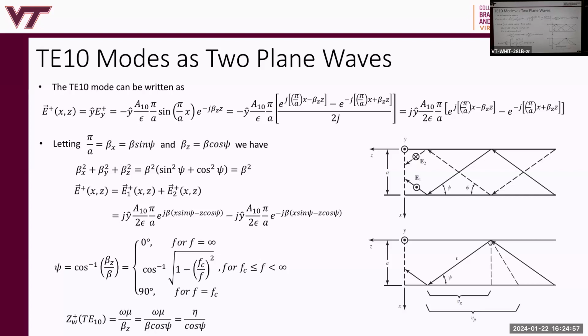So if I designed something like that in simulation and wanted to measure the reflection coefficient in an infinite environment, then I can use a waveguide. At the end of the waveguide, I place inside of it, filling it up, a unit cell, maybe some kind of patch antenna. If I just have a small patch antenna and I put the waveguide right on top of it, the PEC walls are going to image that patch antenna in both directions by image theory. So I'll get an infinite array out of that.